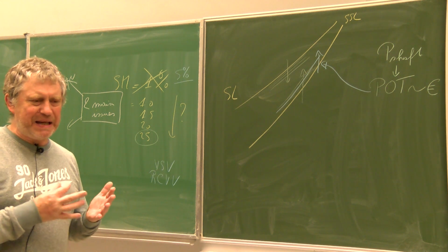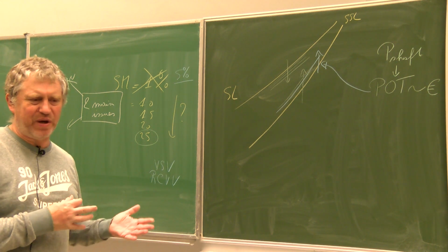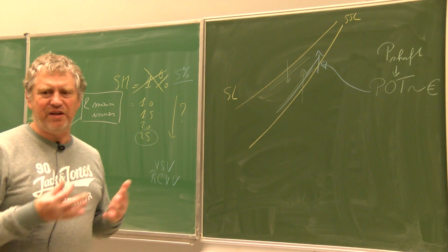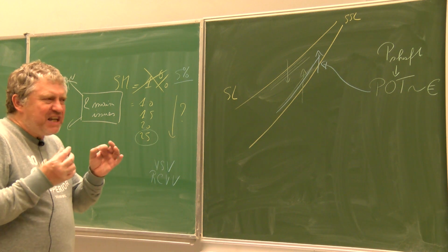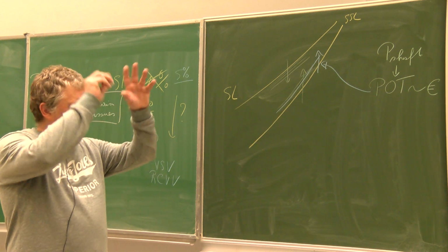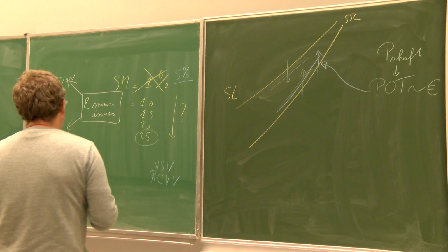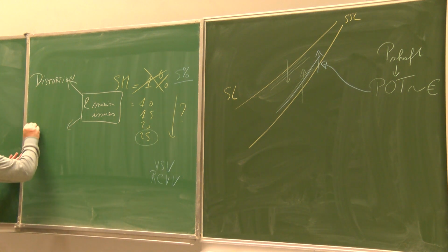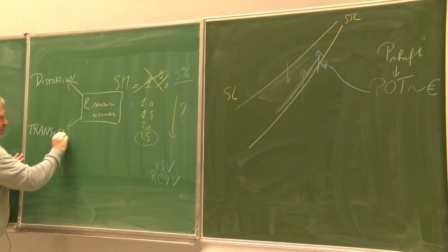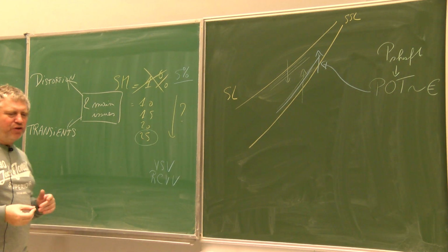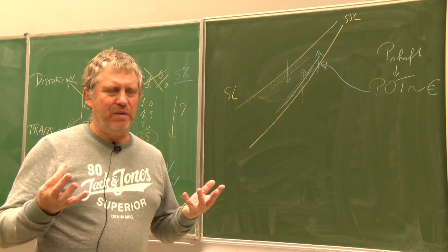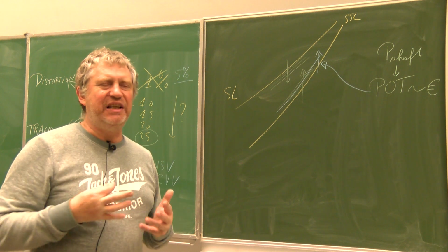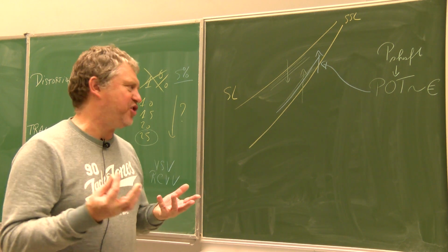So not the same speed, not the same angle, not the same mass flow rate, not the same pressure or temperature on each square centimeter of this front section. And the second reason is what we call the transients. That means the variation of the rating, the variation of the flow, the fact that you change the operating point of the engine.